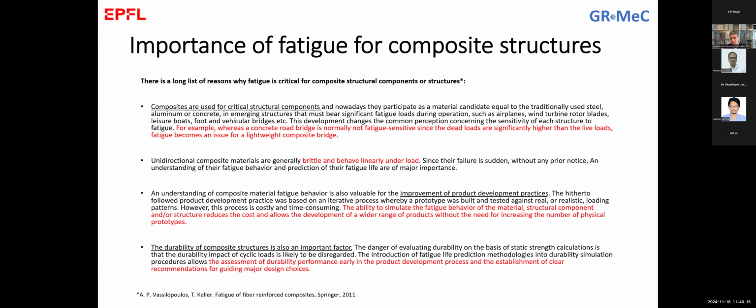So the ability to simulate the fatigue behavior is very significant, especially if you can reiterate fatigue design, so reiterate design concepts to end up with a structure that is able to sustain the loading that is needed for the entire lifetime.